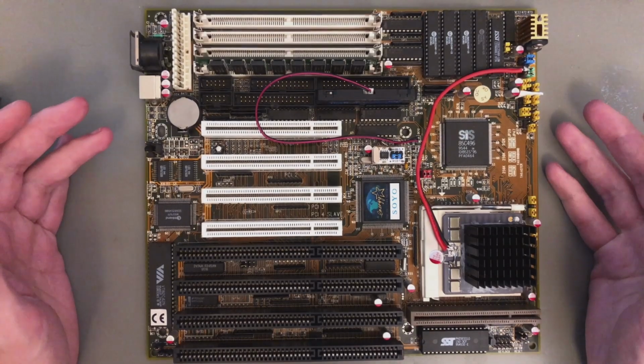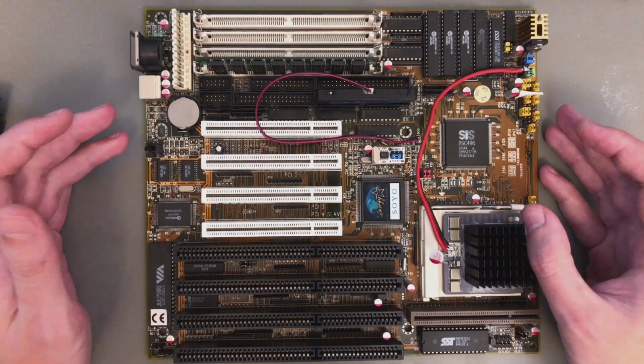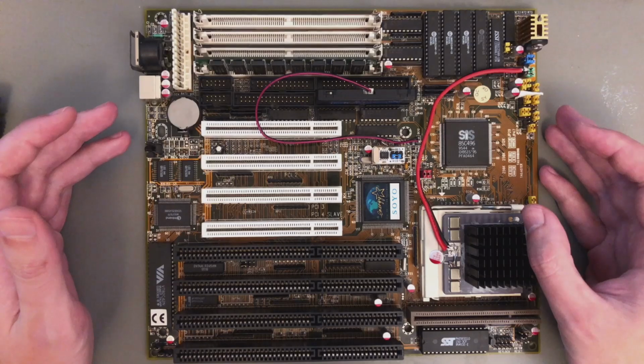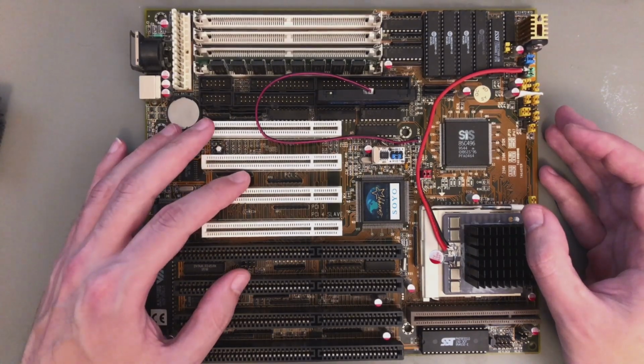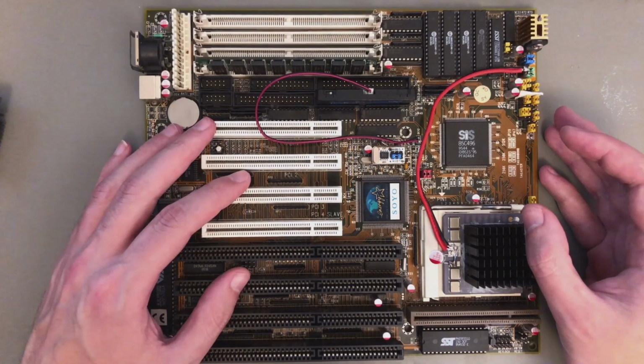So here we are, we did it. A Pentium CPU on a 486 motherboard, clocked from 2.5 MHz to 110.6, and yeah, okay, basically everything between. And a system now that can run everything from the first IBM-XT games to even Quake. And actually way better at this compared to our previous attempt with the AM5x86. So yeah, I can only be happy with these results.